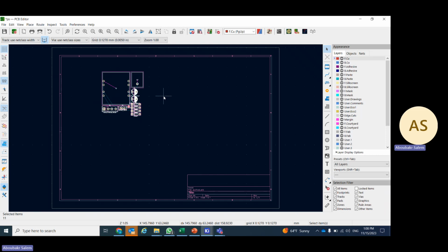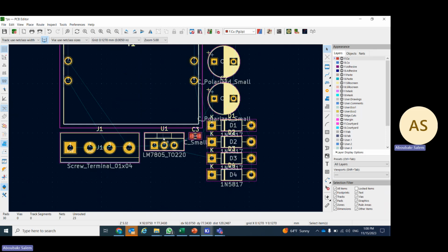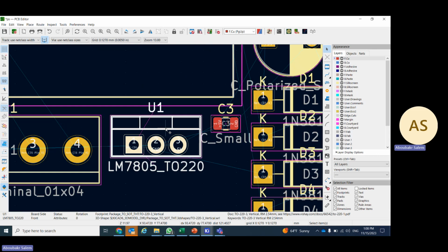So we have what's called auto fit. Auto fit is going to fit the components, but still it may not be the proper way. So the best way is you should place your elements on the board according to your understanding of these components. For instance, can you see here, guys, where is the regulator? This is U1, this is the regulator, okay?